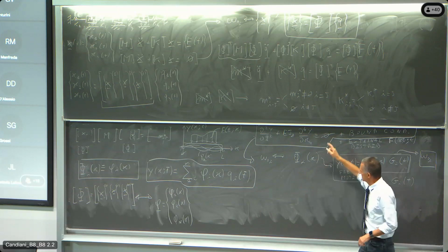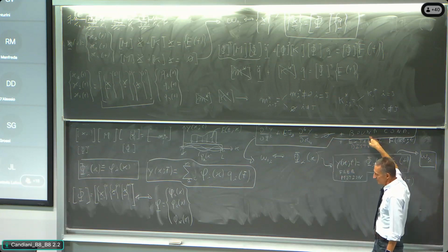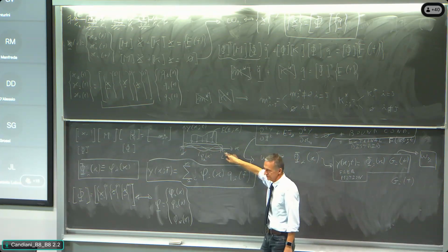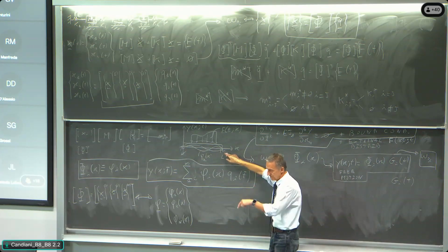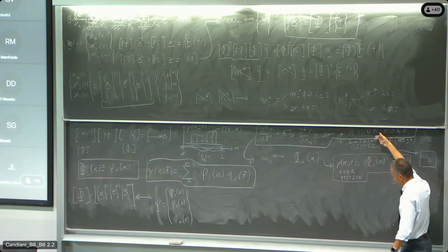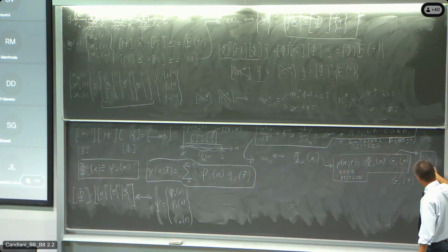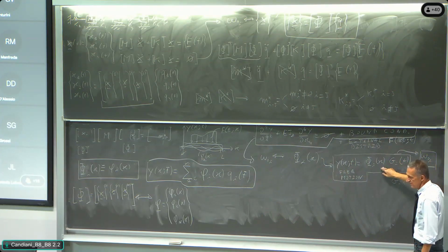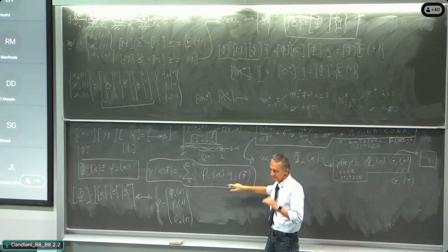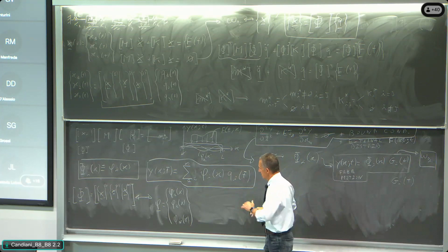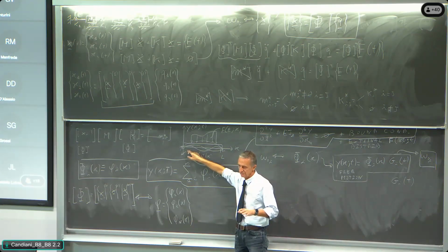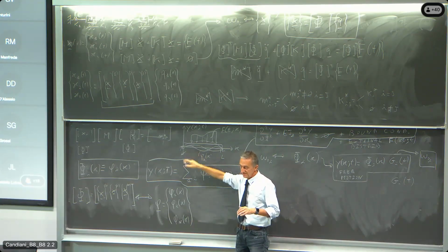But then on top of that, we are fixing that the boundary condition must be satisfied. And having satisfied the boundary condition, we find out the natural frequencies, we define the modal shapes, and all those modal shapes satisfy the boundary condition. So for sure, superposing all of that, I am always making a drawing that is perfectly satisfying the boundary condition. All right? That is the fundamental point.